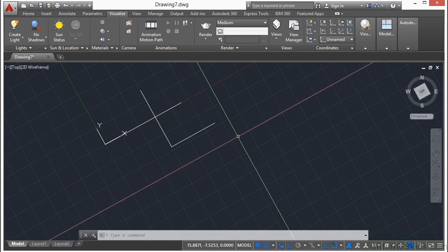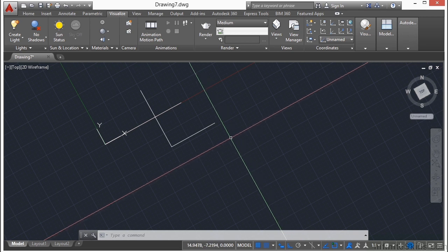Now, when you work in 3D, the UCS is key. There's a function called the Dynamic UCS feature that will automatically change your UCS to match the face of an object, allowing you to draw on that same plane as the object is selected. That's probably one of the most commonly used cases of changing your user coordinate system, when you're working in 3D. Now, that's getting a little bit heavy for this course, but it's hard enough to keep track of just 2 axes, much less 3 or 4 or 5 different coordinate systems that you might want to use.